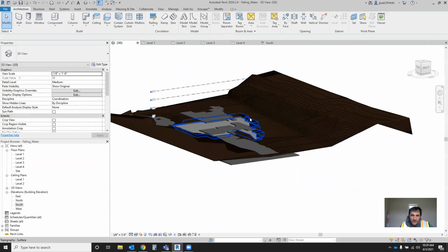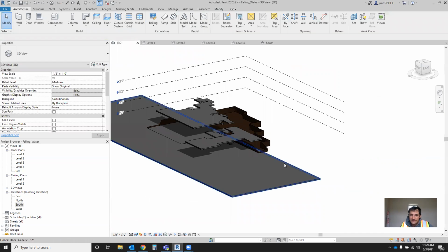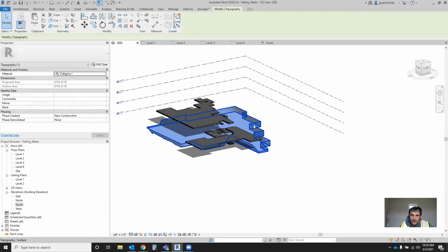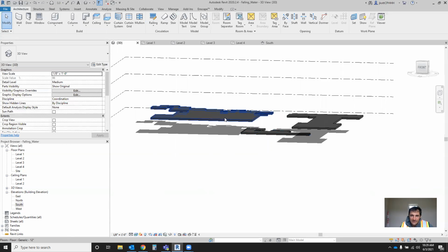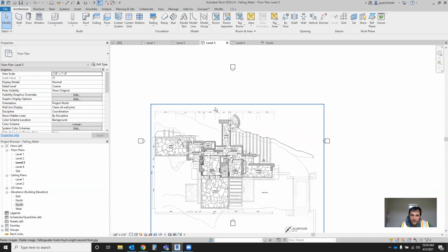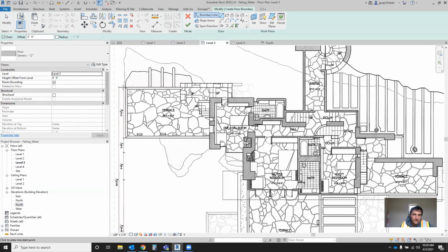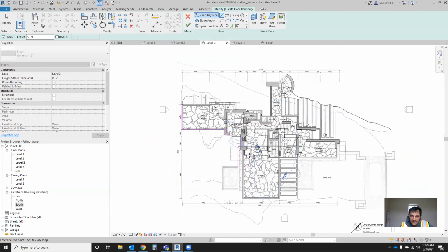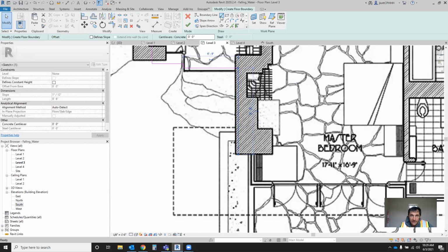If we look at our 3D view, it's starting to take shape. Like I said, we're going to have to adjust this later. So let's just hide all these other elements out of our 3D view. And we'll just focus on the building massing for now. So you can see that first floor basement, second floor, we'll come to the third floor and another complicated floor plate, but we'll just work through it in the same way. Massing everything out, draw the floors in. There's all kinds of little doorways. Oh, I went the wrong way. We actually want to come into the building over here.